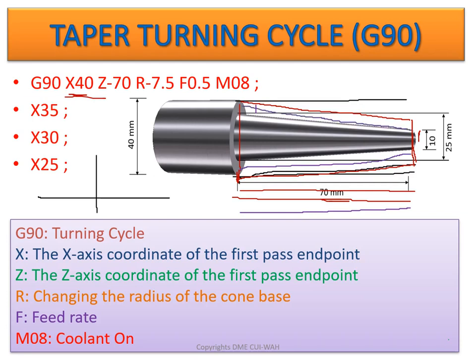So in the first cycle the diameter was reduced, and no diameter was reduced at this side, but in the second cycle here the diameter is now 35 mm, and at this end the diameter will now be 20 mm, 2.5 from above and 2.5 from the bottom side. So the total diameter removed will be 5 mm from the right end, and at the left end 5 mm is removed from the 40, which brings it to 35 mm.